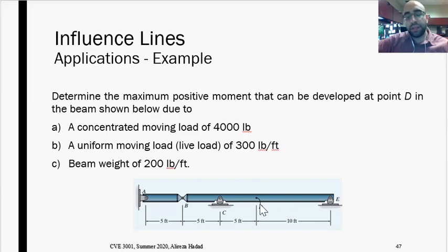Over here, we are talking about bending moment at D. So I said when we are removing the moment restriction, it means that we can simply apply rotational deformation at that point. In other terms, we can assume there is a hinge over there. By removing the rotational or moment restriction, it's like applying a hinge at that specific point. Then we can grab that hinge and pull it up. The deformed shape that you see on the structure is the bending moment influence line for that point.